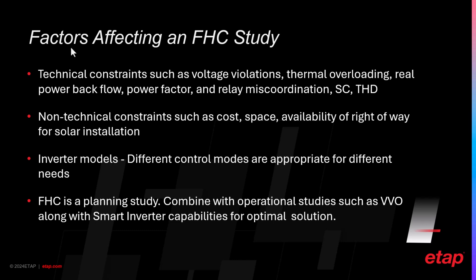Apart from these factors, how you model the system and how you model the most critical element in this context, the PV array and the inverter, that very much matters, because the inverter model in ETAP has plenty of control methods like voltage control, swing control, smart inverter control, MVAR control, power factor control, and different modes are appropriate for different needs. So you would have to consider the effect of the inverter control and its contribution in a very significant way, and they affect the results.